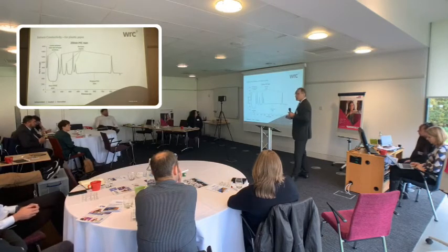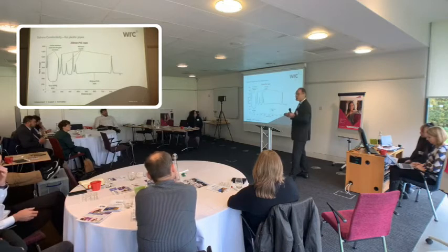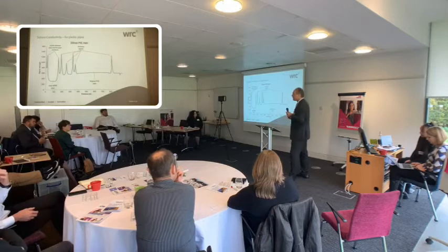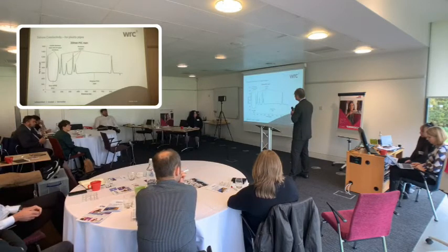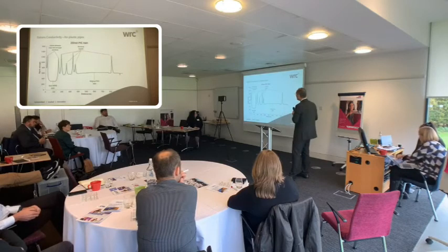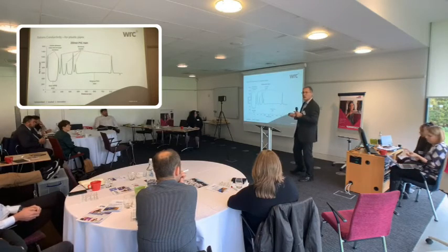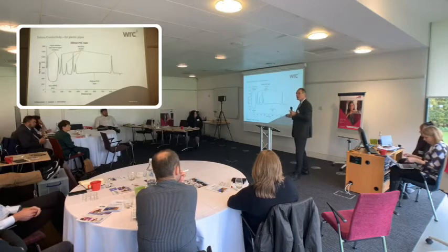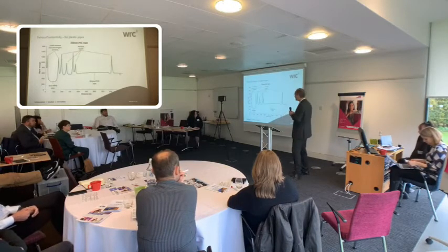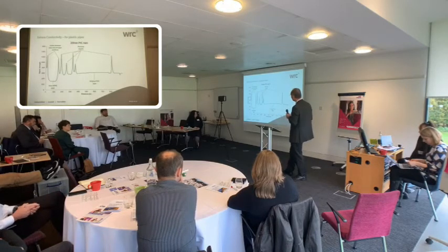We've also developed the sensors for Sahara, and we have a sensor which can be used on plastic pipe. Although we can use the acoustic method perfectly well, we find that actually you can use an electrical conductivity method to find leaks in plastic pipes, and that'll also pick up metallic fittings, so it can tell you whether your leak is at an air valve or at a previous repair potentially. So it's additional information that you might get from carrying out that survey.